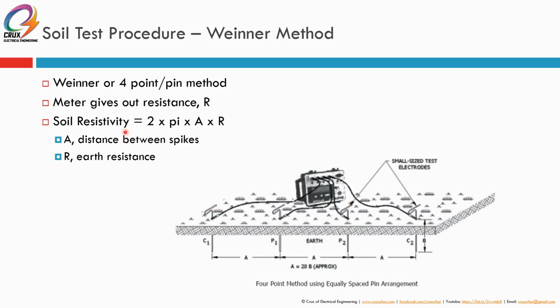So for you to know the soil resistivity at 1 meter, you will put your spike at 1 meter depth, with 1 meter distance between each spike. You will repeat this up to maybe 30 or 40 feet or 20 to 30 meters, depending on if you are going to install a deep well. So normally you go up to even 30 to 40 meters. You do this, for example, every 2 or 5 meters. So every 5 meters, you will measure.